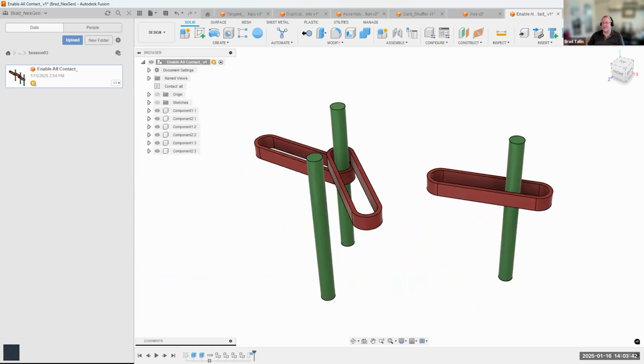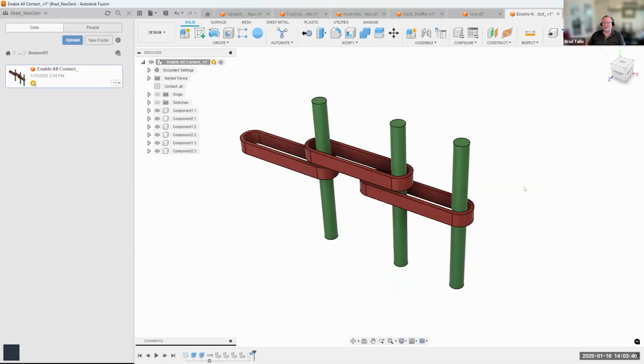And this is a simple example. Think about threaded surfaces and threaded mating surfaces and all kinds of stuff. So you wouldn't want to do something like that with threads. Now, other things: I worked with a customer who does reclining seats in airplanes. They use this situation for seeing how the tracks move for the reclining seat. They'll use the contact sets for that. But you could try the tangent relationship. Again, I wouldn't even use tangent relationships for threads. I'd have to play with that, but I'd be nervous with something as complicated as how many faces there are on threads. And yes, Steve, thread pitch would be one divided by TPI of the screw. Yeah, good point.